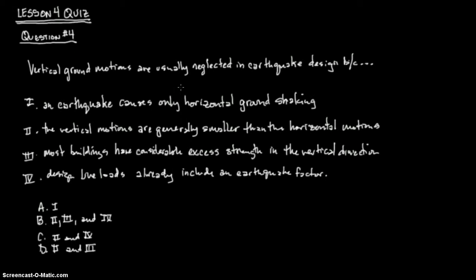Most of the other horizontal or lateral forces, wind is your other big lateral force. Other than that, off the top of my head, I don't even think of any. What you're going to design the earthquake forces for is typically just to not kill anybody, in other words. The earthquake will not destroy the building, but it will damage it. And that's okay as long as it doesn't have a catastrophic collapse. And you might have to repair a lot of things.